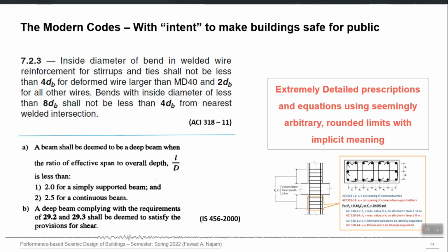So you will use such an approach to actually prove to the client that if this much of an earthquake occurs, this design is going to ensure that no one will get injured, and this process will be under the umbrella of performance based design. And obviously at the end of this whole process there will be a peer review also. It's not that only one party or one firm or one expert will perform all that. There will be a third party review also, that is an integrated component of PBD. So there is no PBD without peer review, right.